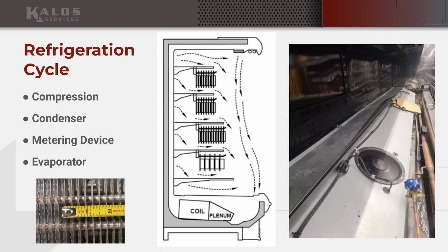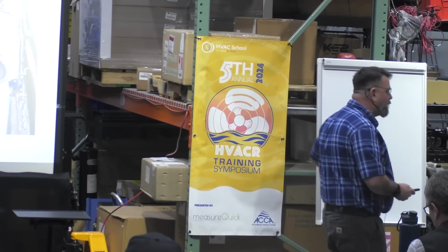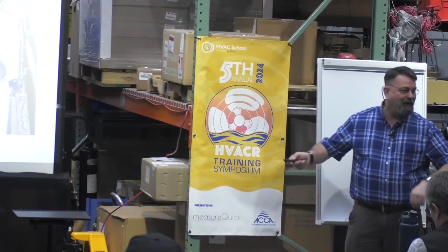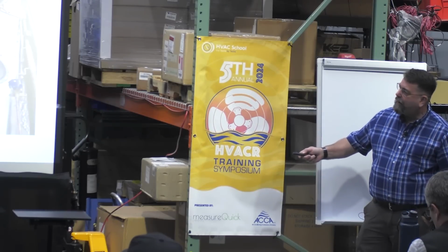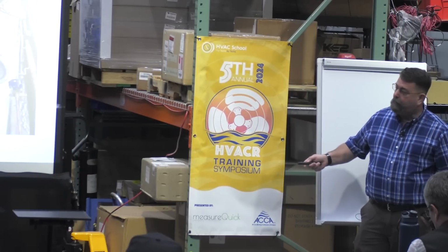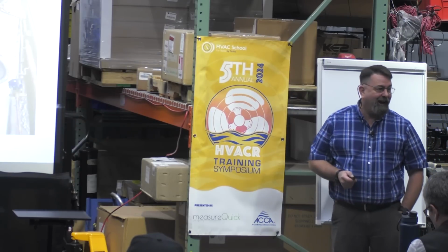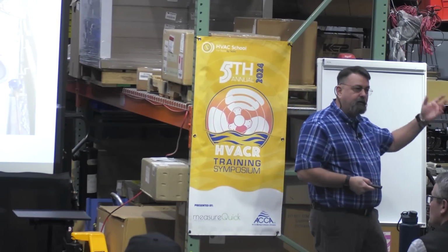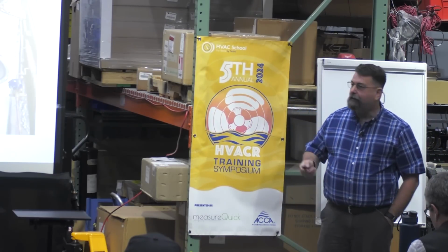It's going to recirculate, okay? That's why I can predict the temperature of that supply air, because if everything's working correctly, I'm not spilling a huge amount of air out onto the sales floor and then pulling in nice, warm, moist air, heavy load, that I'm going to try to refrigerate. I'm recycling the majority of my air, so I can predict that 10-degree difference, or 8-degree, or 6-degree, whatever it might be.